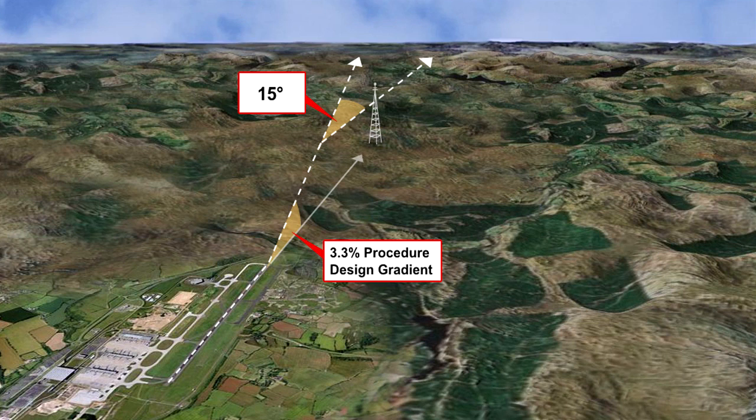This procedure will assume that pilots will not compensate for wind effects if using radar-vectored departures, but will account for wind if on a departure route that is expressed as a track to be made good. Unless radar vectors are specified, pilots should assume they must take the wind into account to follow the track prescribed in the procedure.